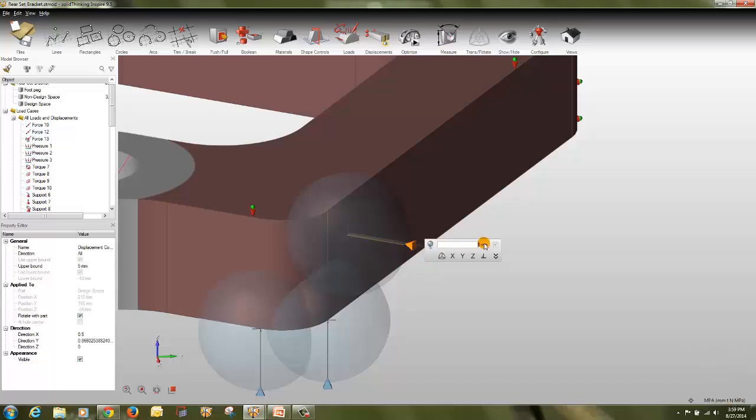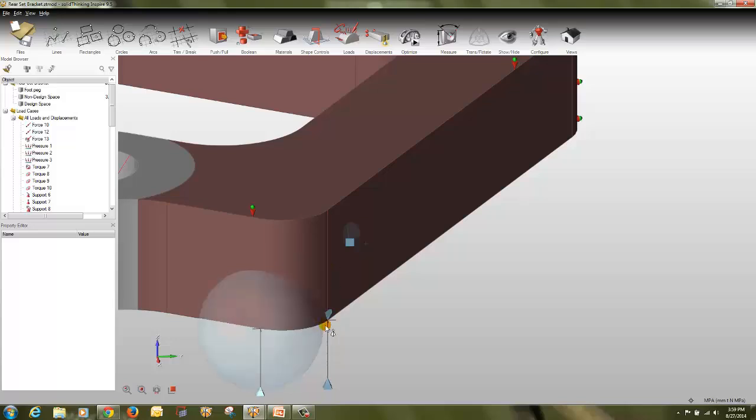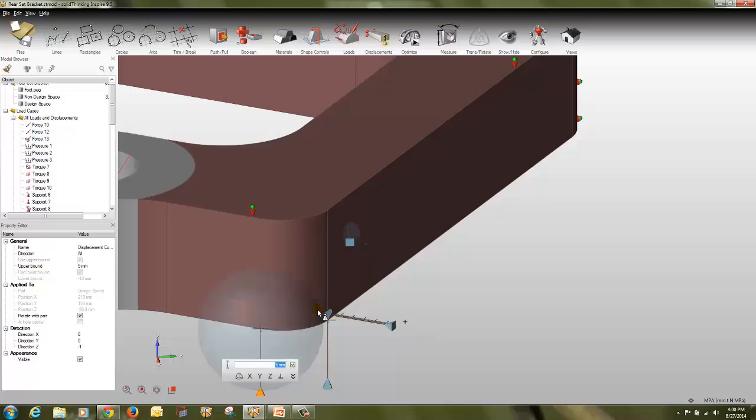I can make it in mm. You can reduce the size to 1. The direction, and you can change it to double displacement, so it will not displace in this. So it is allowed to displace further, but now if it's a double displacement, it will not go further. It will only displace in this region, not more than that or less than that. So this is fixed, this is fixed. If you turn off, it's off. If you turn it on again, it's on. So you can turn off this, so it's fixed.